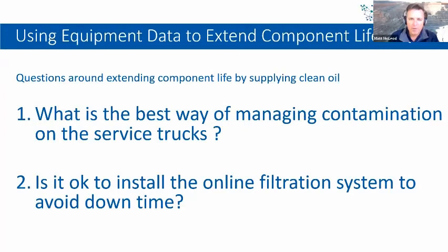Other programs I've seen start a testing regime for maybe 3 months, where you look at the bulk fluids coming onto the site, your bulk storage, and the transfer systems from bulk storage to the workshop or to the service truck, and actually quantify if contamination is being introduced somewhere. Let's find out where it is so that we don't waste time, money and resources chasing the wrong thing.